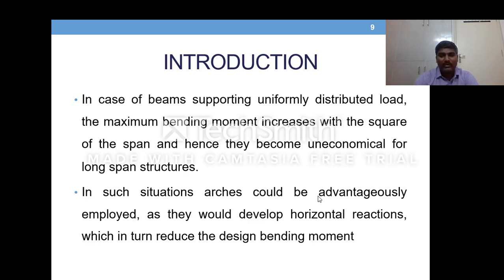What do we do if the span is large? In such situations, the arch can be employed, which is advantageous. How is it going to be advantageous? We will see that the arch will develop horizontal reaction. That is the prime reason to reduce the bending moment.